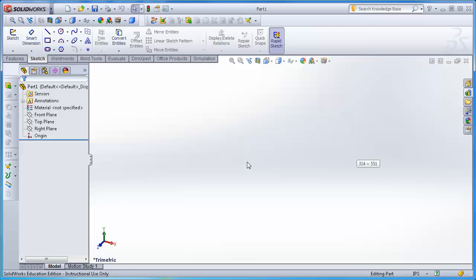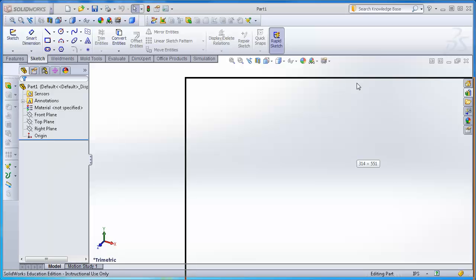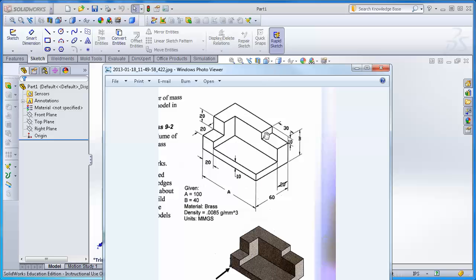And so the general idea of creating a part is typically draw a sketch, hopefully completely dimension the sketch so that everything is totally known and not left to be floating around. So draw a sketch and then either extrude that sketch in a straight line to make a solid, extrude it in a straight line to make a cut, or maybe extrude it about a center line to make a circular solid or a circular cut.